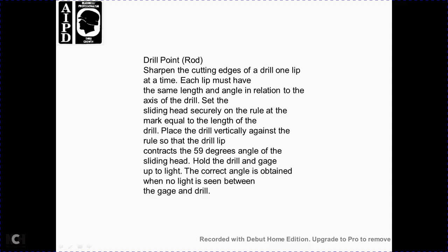Drill point gauge. Sharpening the cutting edge of the drill: one lip at a time. Each lip must be the same length and at the same angle relative to the axis of the drill.